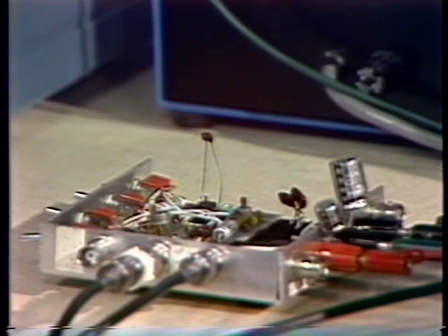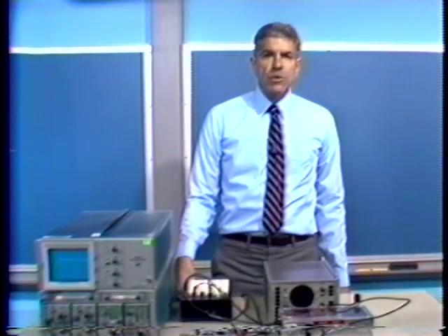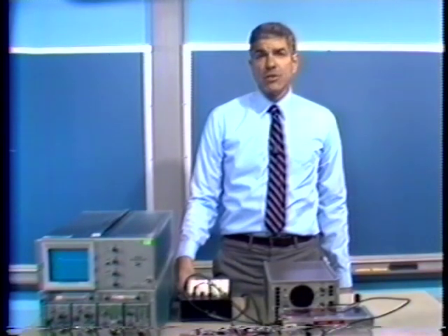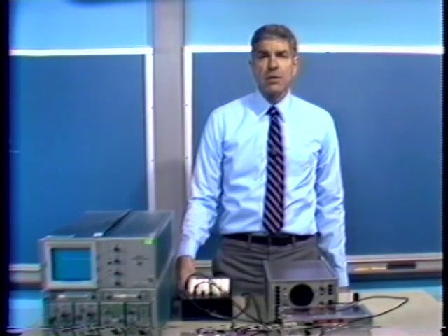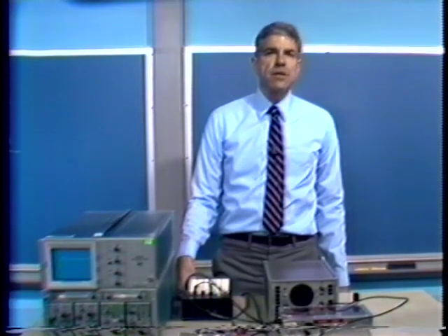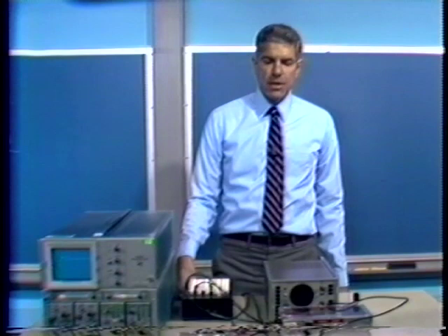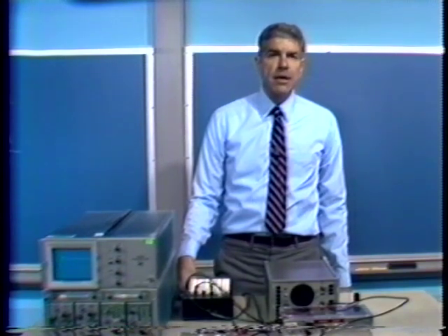If you look at the schematic for that amplifier, there's something like 13 transistors in the forward gain path. Consequently, if we investigated the amplifier using any of the common transistor models, we'd conclude that there were 26 energy storage elements, 2 capacitors associated with each transistor, in the gain path.